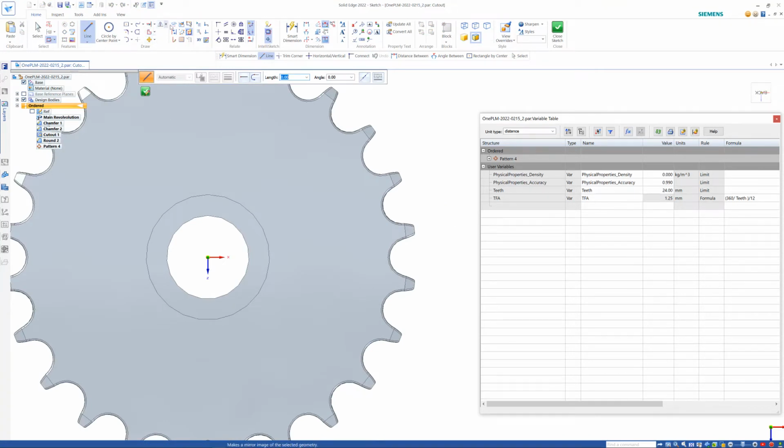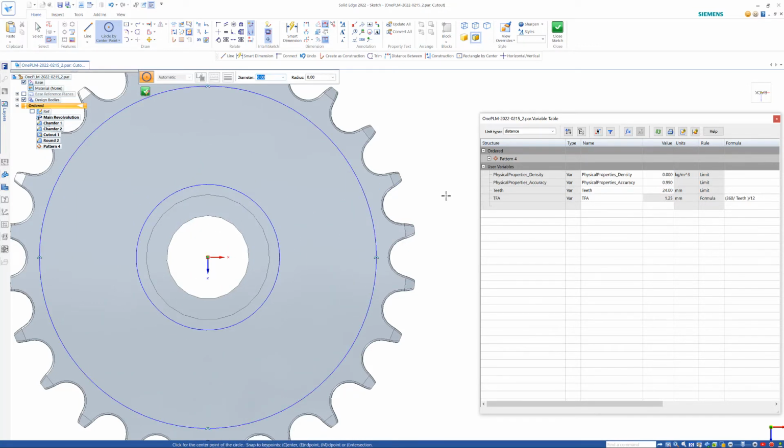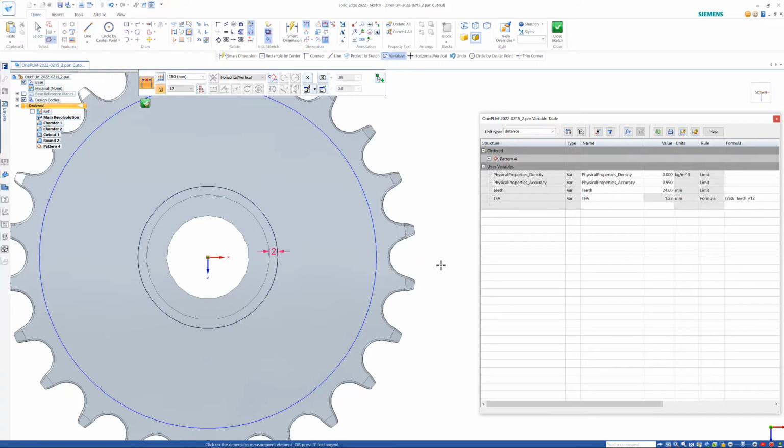So for this one, I'm going to start a circle from the center point, and I'll do another one from there. So for these, we need to dimension these up. We could do this all sorts of different ways, but I'm going to dimension that to that solid 2mm. Could do symmetric offset, project with offset, or all sorts of other stuff, but just to keep it simple, dimension that to there, and we'll go 8mm from there.